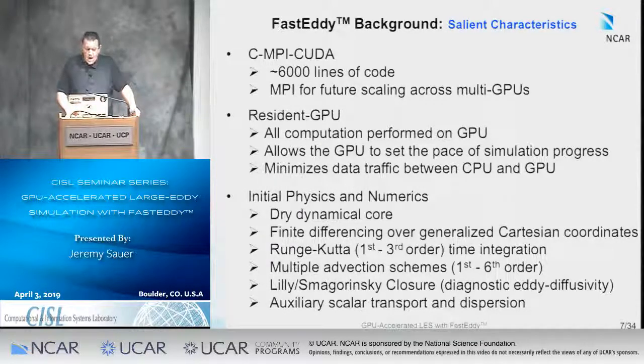We use a Lilly-Smagorinsky turbulence closure scheme, and at this time we have a diagnostic eddy diffusivity as opposed to a prognostic TKE-based eddy diffusivity. And then we add in some auxiliary scalar transport and dispersion.